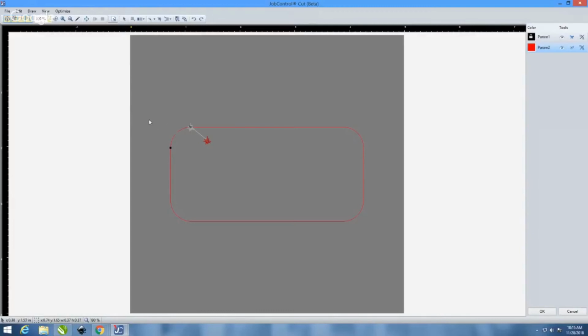So possibly you can save time with this, or maybe you have a piece of material somewhere that is higher than the material you have in your laser. So you wanna avoid that piece because your laser head will hit it. So you can rearrange these laser tool paths to go around that raised piece. And there's many other applications why you would want to use that.